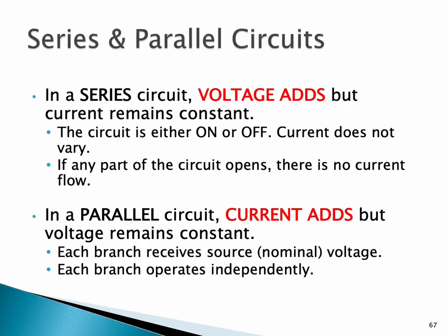We've talked about series and parallel connections. We'll be dealing heavily with series connections coming up next week when we do our calculations. As we do series connections, positive to negative, current stays the same, voltage goes up. Parallel connections, when I connect positive to positive, negative to negative, current is additive, voltage remains the same.